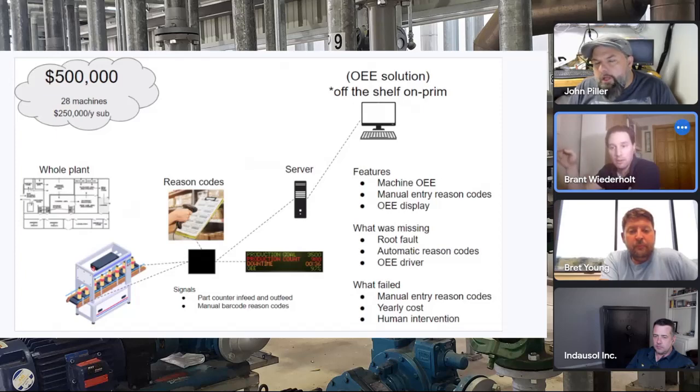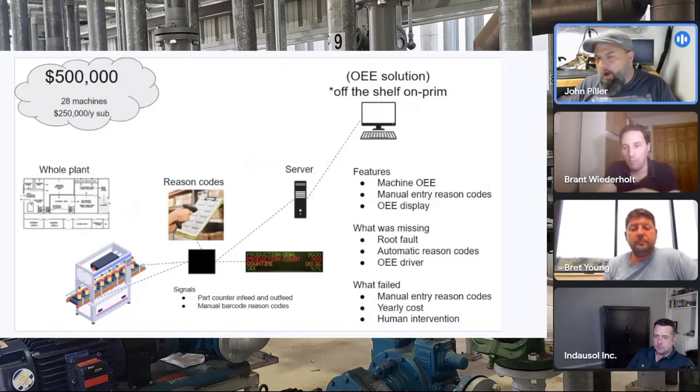Sure. So some of it, if there was a more modern PLC, they used that term, and it made me laugh when they used that term. But if it was, let's just use an S7 or a ControlLogix, right? We had an Ethernet port on it. Normally, we were able to pull that memory and pull it into an OPC.